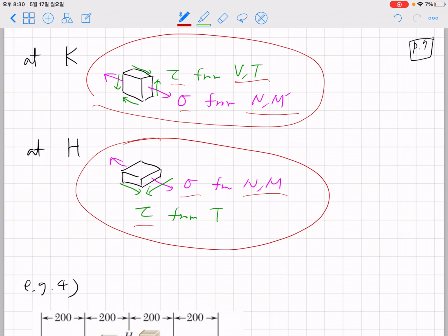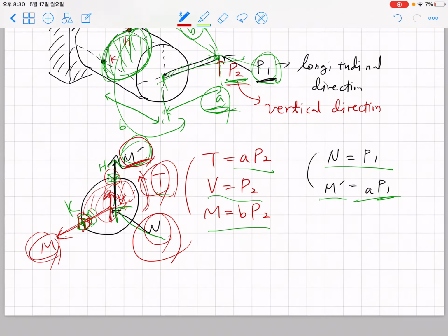If the problem asks for full three-dimensional analysis, you do a three-dimensional Mohr circle analysis and find the maximum shearing stress and principal stresses. By comparing that with the normal strength and shear strength of the material of the structure, you can say whether the structure is reliable or not. That's how to approach a problem combining all four reactions in different directions.